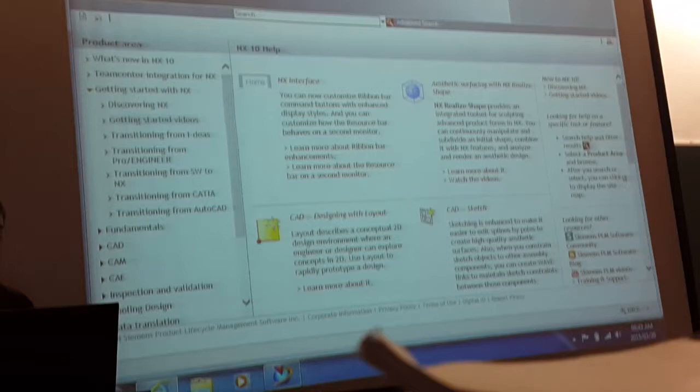There is a simpler FEA tool called Design Simulation, right? And that's based on a streamlined version of NX Nastran. So it's for very simple analysis, and this kind of analysis would be suitable for us to be using design simulation, but I'll go with the more general case, advanced simulation. Okay, so click on that, and it takes a while to open up advanced simulation, and automatically brings the part into the simulation environment.